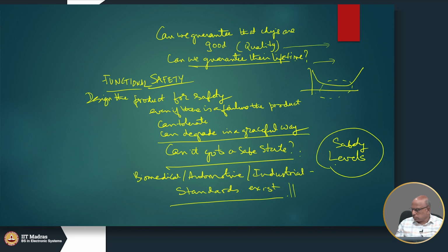Okay, so we have discussed two important points, reliability and safety, and how stress testing can be used to assess reliability, and how things like Shmoo plots and data from the fabs can be used to learn about what could be wrong and fix the issues.